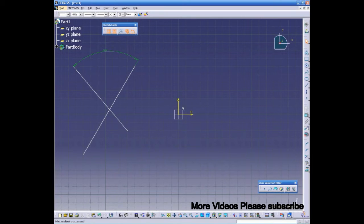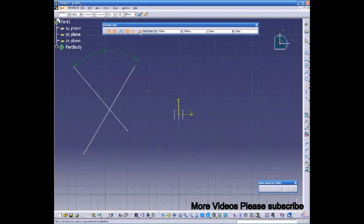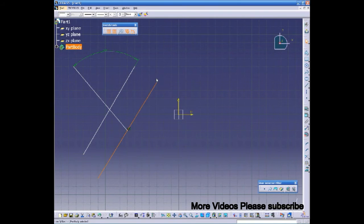Click the line icon. At the same time, activate Symmetrical Extension option. By activating this option, every line that we create will be mirrored in the opposite direction automatically. Click anywhere to define the starting point, and drag the cursor to pick the ending point. You see now, line in both directions is created. OK then. Now, let's try more professional work on the line.